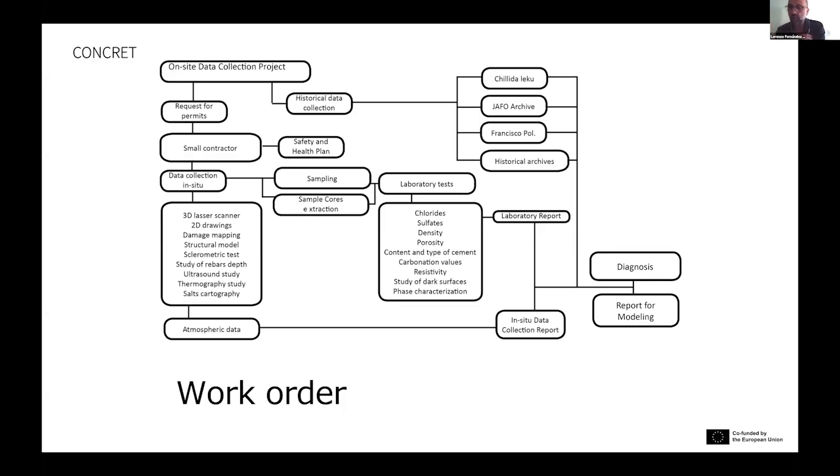As I understand, the other participant has said the main problem always is how close the rebar is to the surface. So if you have a concrete in which the rebar are deep, you won't have a problem even if you have carbonates, chlorides or whatever problem. So the problem is how thin that protection is and where the rebar are.